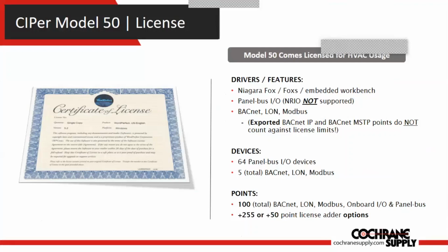In terms of the point count, you get 100 standard points. I call them, they're more universal points. So it's BACnet, LAN, Modbus, your onboard I/O, as well as your panel bus. Now I know as a plant controller, that may be somewhat limiting, but you do have the ability to upgrade to the point license adder options, and you can add in increments of 50, or if you want to go all out, you could add a 255 point license.